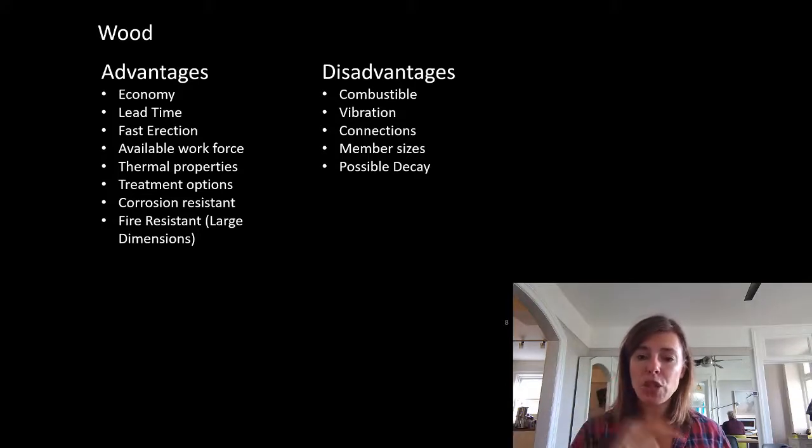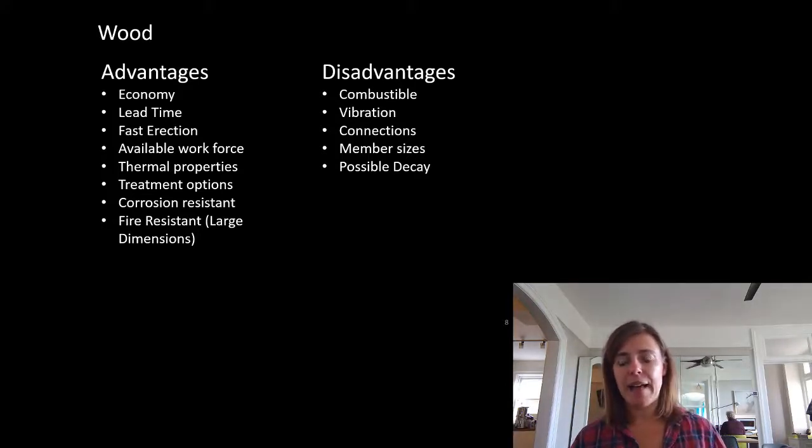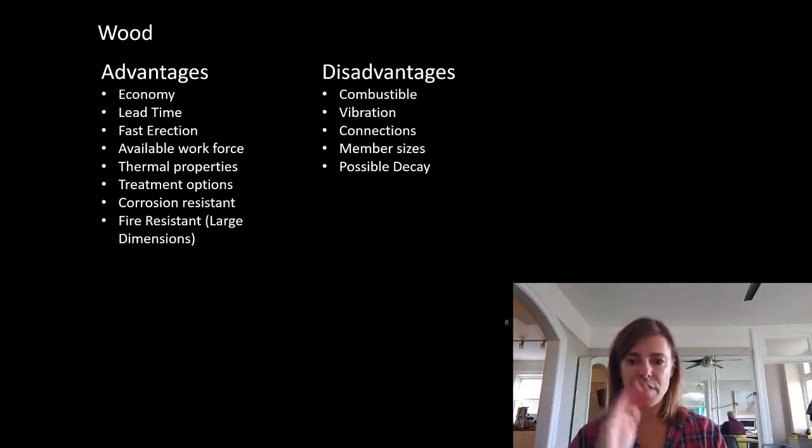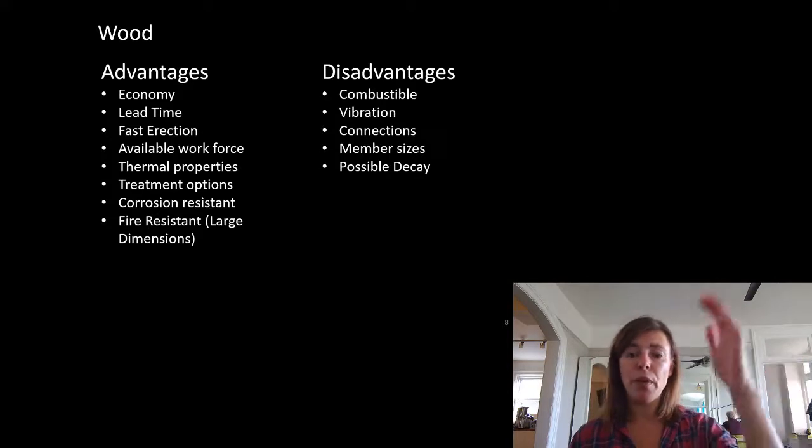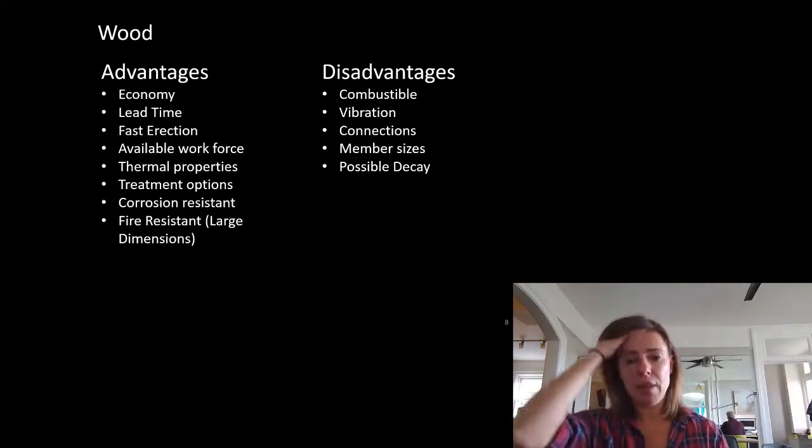That is a much bigger way to have a kind of a thermal problem in your building, which is why we have double and triple pane glass. I'm not the expert on that. Obviously, you guys are probably doing a lot of that in your other classes. But a single pane piece of glass is going to be much more willing to lose heat than the wood element in your building.